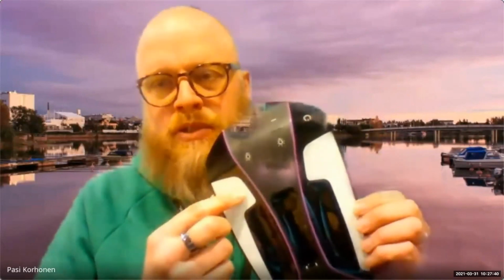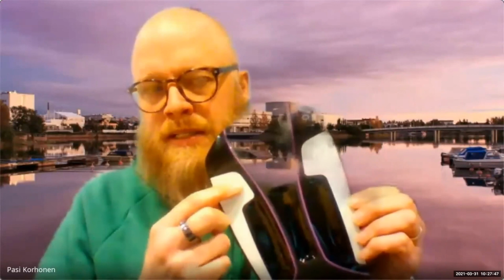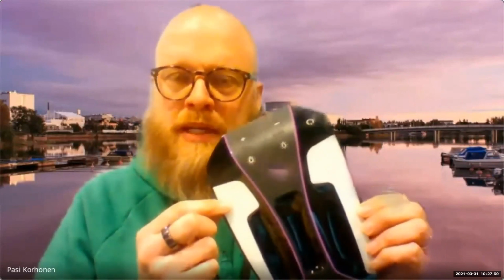So the way we did it was that we had A-film printing, and we made it white, and this has to be translucent since we want the courtesy light out here, and the translucency of the area has to be as high as possible since we want all the illumination performance out of that product. So we need to mix a certain ink set so that this is hiding all the features of the B-film and not showing any illumination defects because of the antenna. And we also ensured that we get the maximum light output from the part. And we managed to create an ink concentration that fulfills both of those criteria.